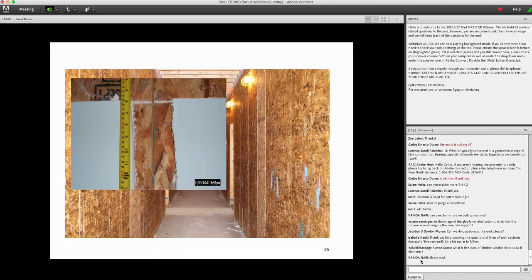That's a long corridor completely sheathed with OSB. You can see a door opening on the right under one of the lights. But on the inset here, I've overlaid a photo where you can see a gap or a joint between two pieces of OSB and some of the nail heads, and the spacing measured out between the nail heads. It is a requirement in the code to have a small gap between the sheathing, so that's good.